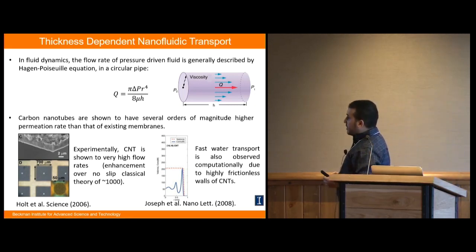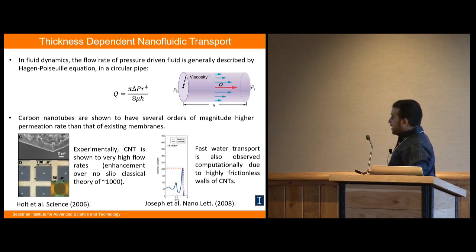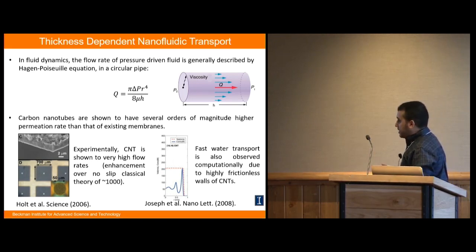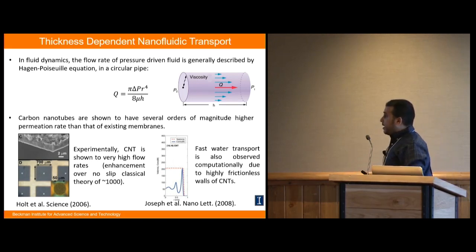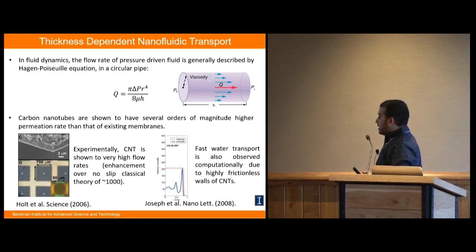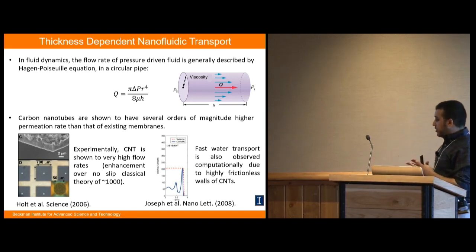One way we were thinking about is to take the confinement effect within the carbon nanotube and how it changes physical properties such as the viscosity mu here. We can enhance this equation by considering the changes of the viscosity based on the radius and the length of the carbon nanotube, as well as the friction coefficient, where at nanoscale fluid systems we experience high slip phenomena.